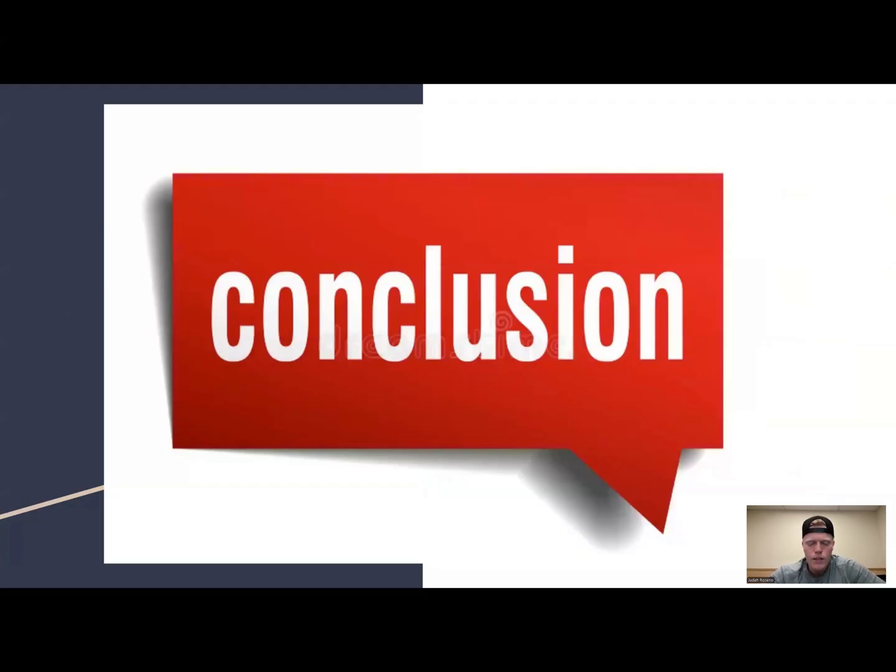So in conclusion, things in reality are a lot different than they are in SolidWorks, and it's important to keep that in mind when you're modeling and using simulations, especially with fixed geometry. Nothing is ever truly fixed. We can get as close as we can. However, it's highly unlikely that things are actually completely fixed.